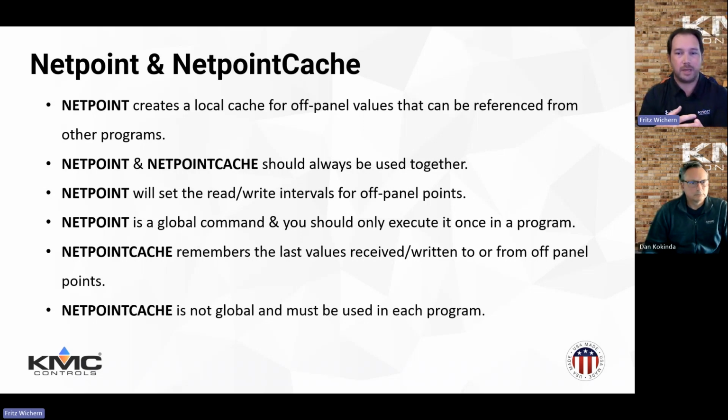NetPoint and NetPoint cache should always be used together. This helps to manage the timing of any off-panel requests, as the controller will handle the wait and interval functions in the background. The NetPoint is a global command, and you should only execute it once in a program. If a point is read-only, on that second part of the syntax, we would use a NaN value in the write interval field, and we'll look at the actual syntax setup of that point in a minute.